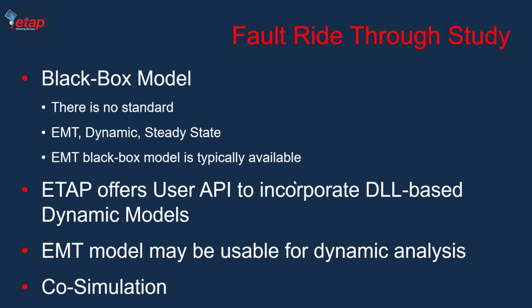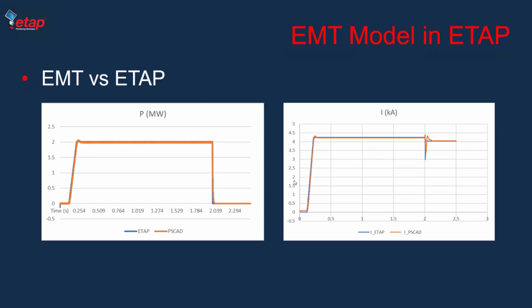The other thing that is important to say is that the EMT model, as we'll see, may be usable for dynamic analysis as well. So what we have done so far, we have taken some black box models, wrapped them using the same API, and managed to run them during the transient stability analysis. This is the result of one of the systems that we ran in PSCAD and ETAP, for the case of a three-phase fault at the point of interconnection.